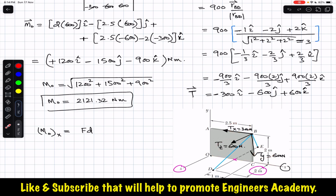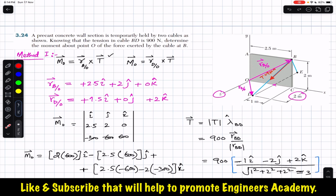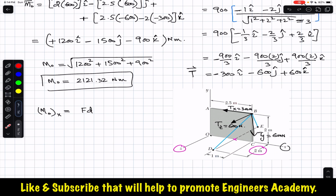So first of all, we can see that this x component is parallel to the x-axis, so it's not going to produce the moment about the x-axis. It can only move this slab in the negative x direction. Since this is acting in the negative x direction, it cannot rotate this concrete wall section about the x-axis. So Tx cannot produce the moment about the x-axis.